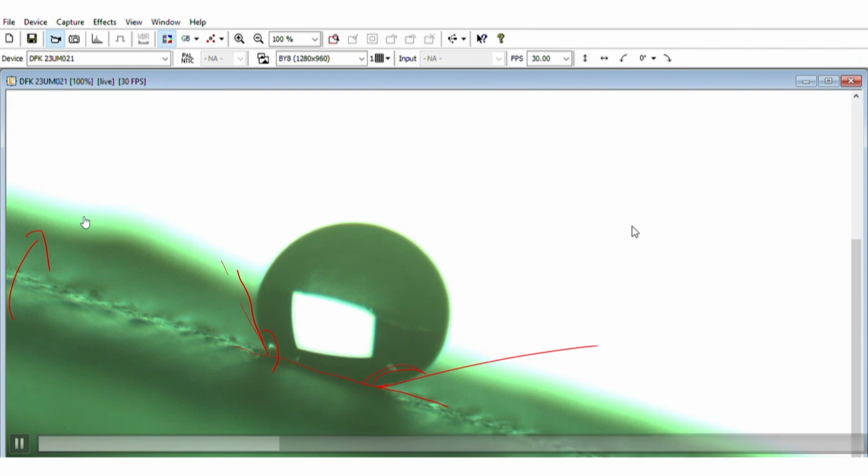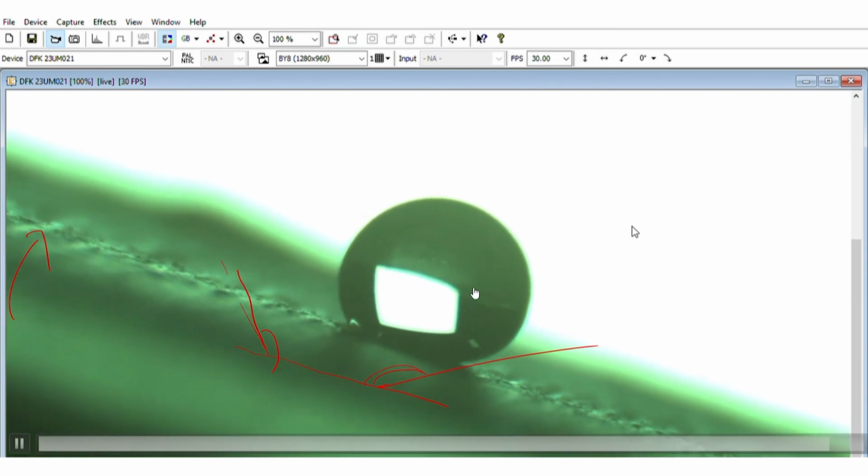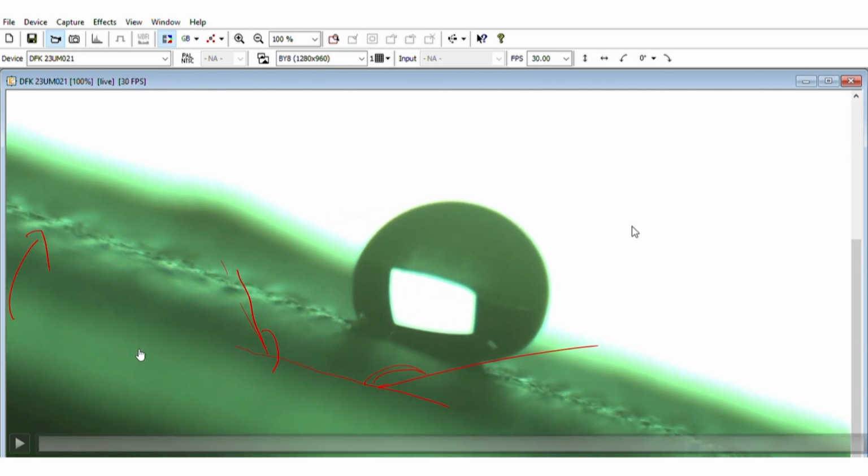So, you can see that this is being pulled on the other side, but still the angle difference increases and the drop remains pinned over here. Again, this kind of surface, which may show a large contact angle, has very high hysteresis, and as a result the sliding angle is also quite high. They cannot be called super hydrophobic surfaces; they are simply hydrophobic in the advancing case. In the receding, the angle may not even be hydrophobic, or higher than 90 degrees.